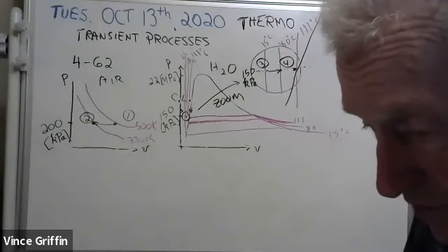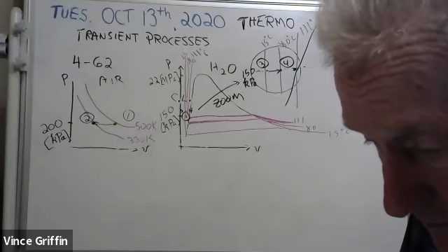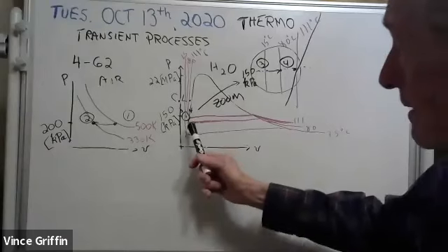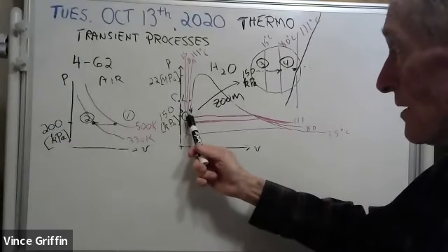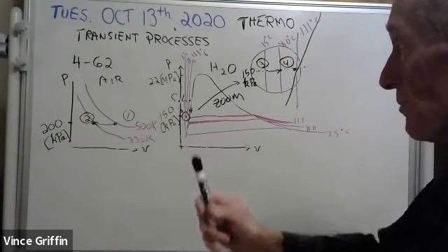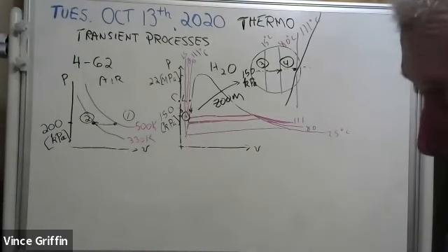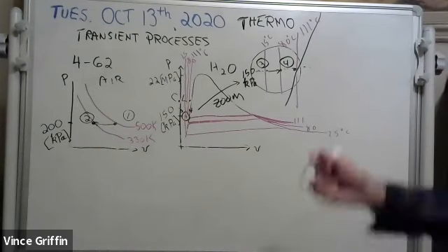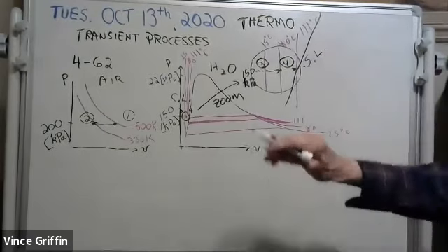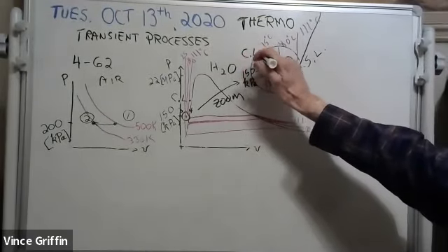Taylor, did that answer your question? I'm still confused. So the 111 is what we found in the tables at 150 kilopascals, right. That'll put you right smack dab on the vapor dome at 150 kilopascals and 111 degrees Celsius. That is what they call saturated liquid. But out in here, we're compressed liquid. Okay, I think that's what I needed. Thank you. Okay, good, excellent.